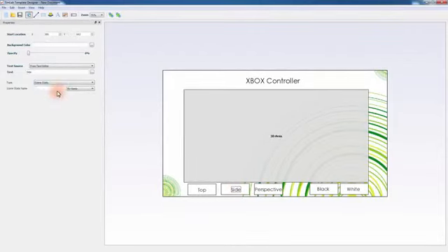In the second tab of the PDF settings, you can select background music to play while the document is open. You can also set a password that will be required to be typed upon the opening of the PDF document. In the 3D tab, you can select whether or not to show or hide the 3D toolbar and the world axes. You can also disable the selection of components in the PDF document.